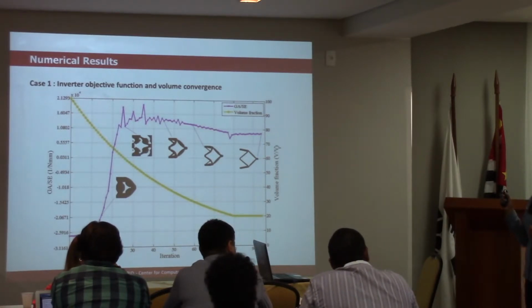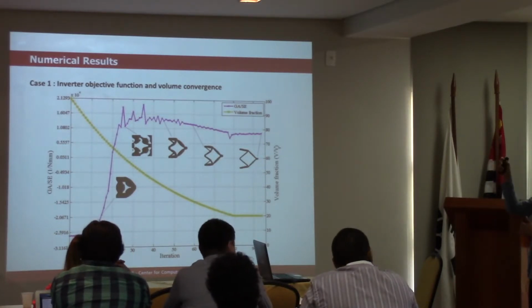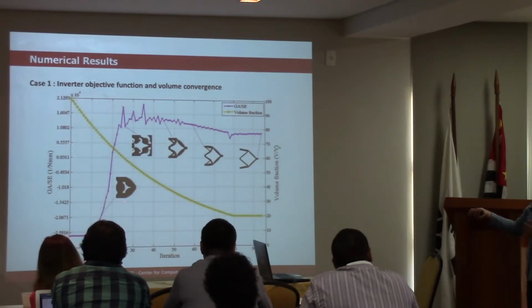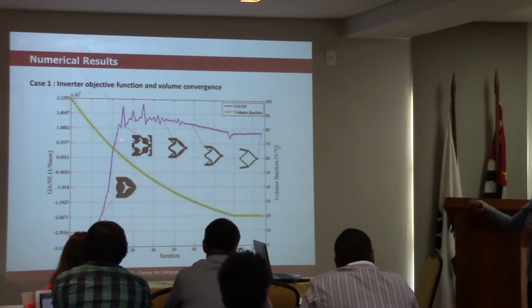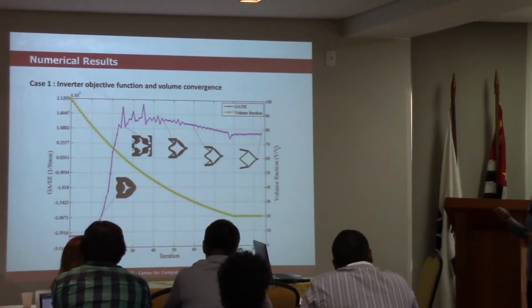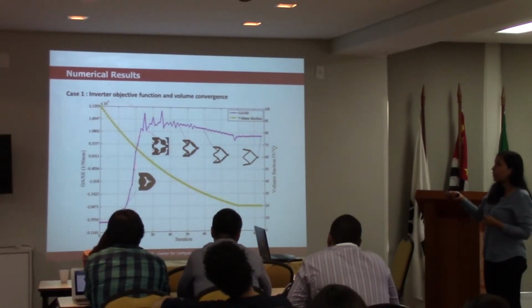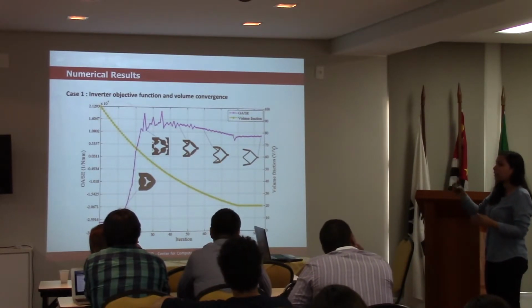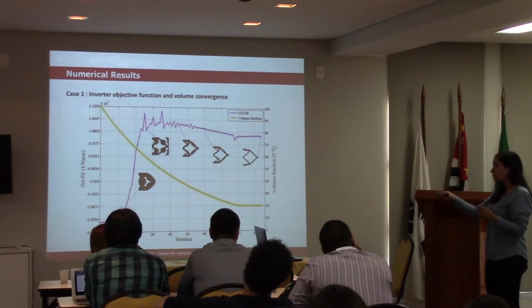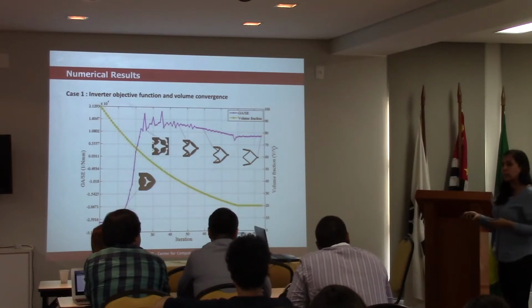We depart with a full design domain. If we started here, it will be all black. And it removes material. This zone here is very interesting, because it did things we didn't expect. And it was important that we were using BESO and not ESO, because in ESO, parts of material that are removed cannot go back. And in this case, it kind of meshes until it turns to the evolution path. So it was very important that it was BESO and not ESO.